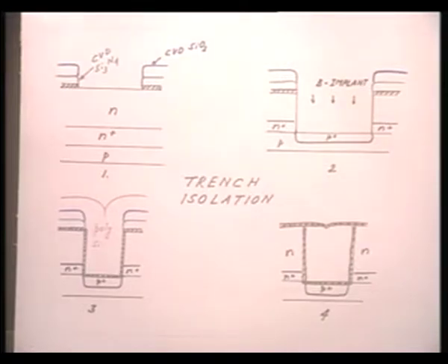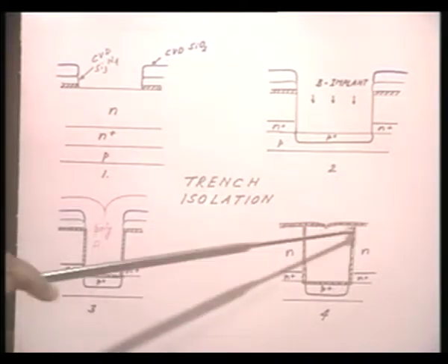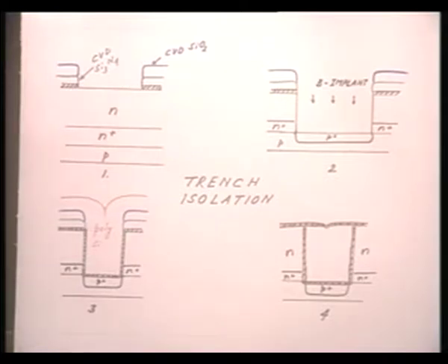Next point is planarization, because topography is very important in integrated circuit. We must have a planar surface. This surface definitely does not look planar, right. So, what we have to do? We have to etch it back. Using silicon nitride as the etch top layer, we etch it back, so that you have the poly coming only up to here, up to the top of the trench. Okay. Then you remove the silicon nitride and silicon dioxide and simply carry out another oxidation, thin oxidation, so that the top of the polysilicon layer is also oxidized.